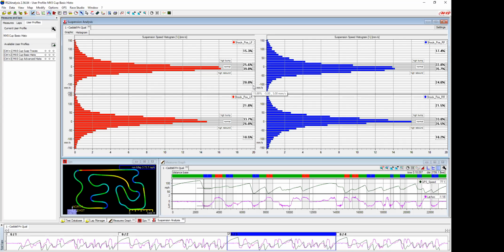Does playing with the shock knobs change 25, 25, 25? Absolutely. That is what your shocks do. Maybe you have a shock that's 1, 2, 3 way adjustable, and every shock is different. But if you have the ability, you would begin to want to adjust the knobs, the low speed compression, high speed compression, low and high speed rebound, to try to begin to adjust these in to that 25% across the board.